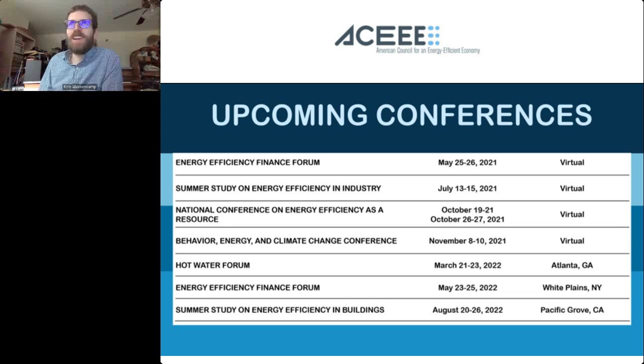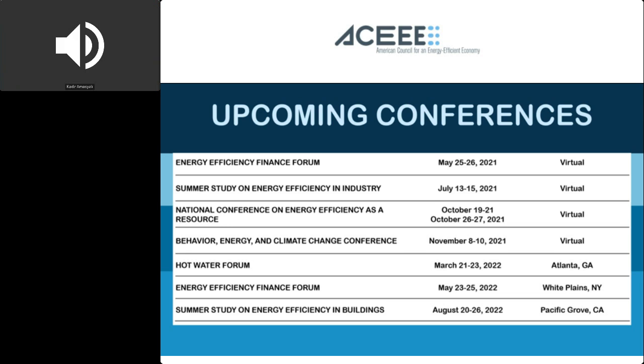Paul Kintner has the same question I did, which is the model looking ahead at what the future water draws are going to be, or just the pricing? For the first RL agent, we didn't consider water draw. We only consider price because forecasting water draw is pretty difficult. But for the comparison of MPC and RL, for MPC, we need to assume that we have the information about future water draw and future price. So just to make our comparison fair, for RL agent number 2 to number 4, we assume that we have information about water draw and electricity pricing.